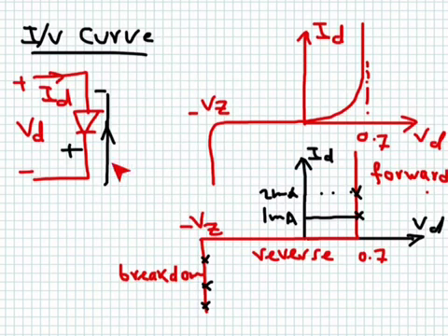So this is the diode here first. We have a voltage, VD, applied between the anode and the cathode. We call this terminal the anode, and this terminal the cathode. When this is positive, then you have a current. A current will flow here only if this voltage almost reaches 0.7. Below 0.7 it is not passing much current. Unlike the resistor, which will pass current even if VD is small, positive but small, the diode will not pass current unless the diode voltage is at least around 0.7.